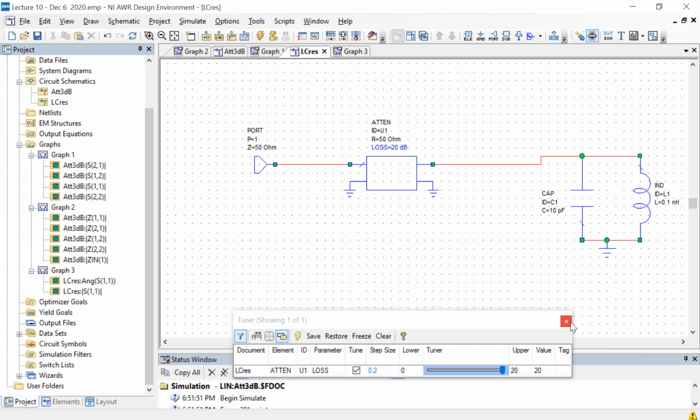And in that case, you are mostly interested in knowing two things. One, what is the frequency when it starts to change, and two, when it is fully transmitting or fully stopping, what is that attenuation, right? So ideally a filter in its transmitting bands would have zero attenuation, but any real device will have some small amount of attenuation. And then when it is rejecting, you need to know how strongly it is rejecting. Is it 20 dB, is it 40 dB, is it 100 dB? Because that tells you how much protection you are getting.